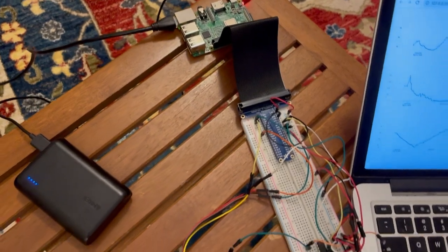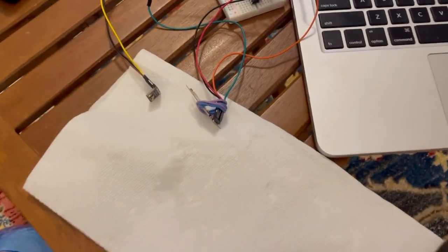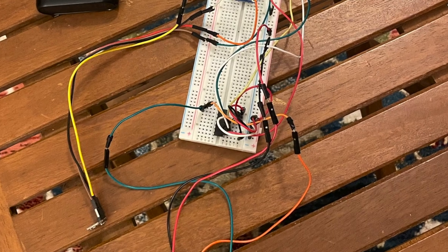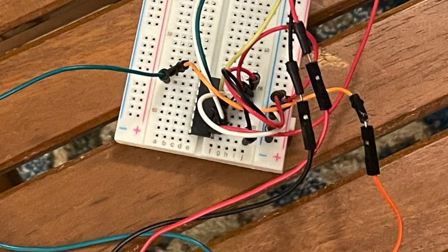The Raspberry Pi is connected to two sensors. There is BME280, which is used for humidity detection. The other one is Wind Sensor Rev C, which I'm using to measure wind speed and temperature. It is an analog sensor, so I also have an analog to digital converter to convert its signals into a digital input to the Raspberry Pi. And as you can see, I'm using a breadboard to wire everything together.